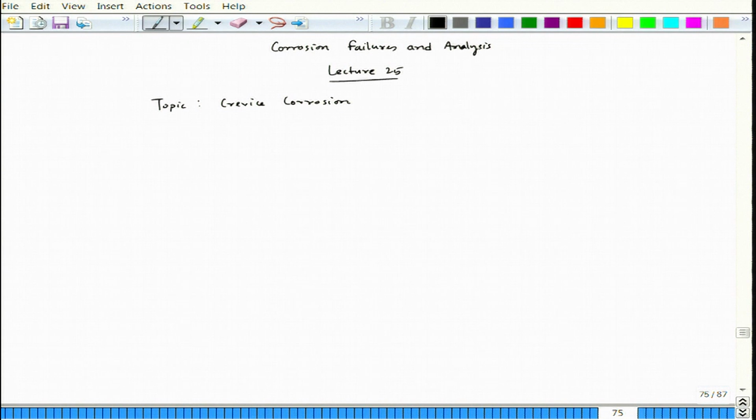Now, at the same time, we have given a lot of examples, the photographs, looking at how the crevice corrosion initiates and how it grows. We have given the example of a door, where the sheet metal is bent over to make a thick portion at the edge of the door, and there crevice corrosion starts. We have also seen an example of a lock, an excellent, highly corrosion resistant lock, it does not matter which company made it.